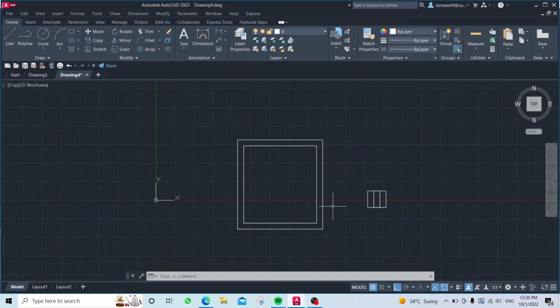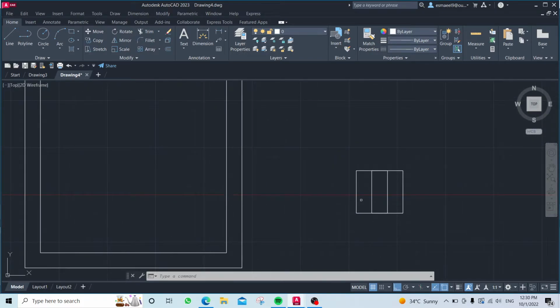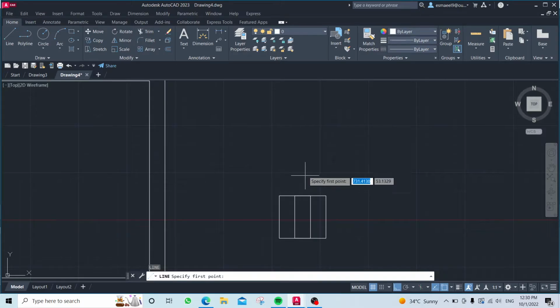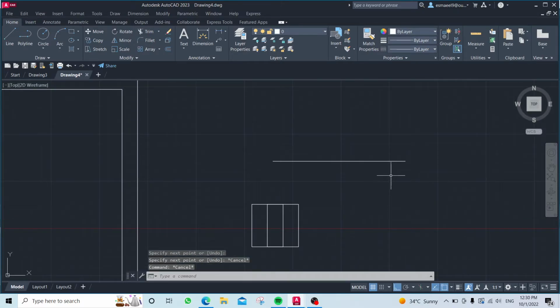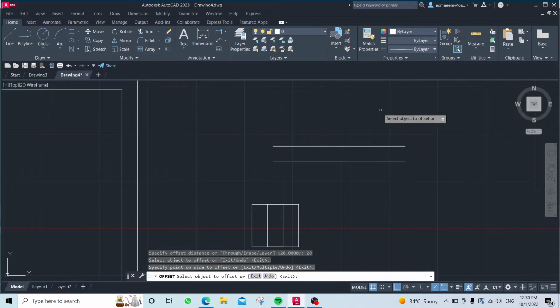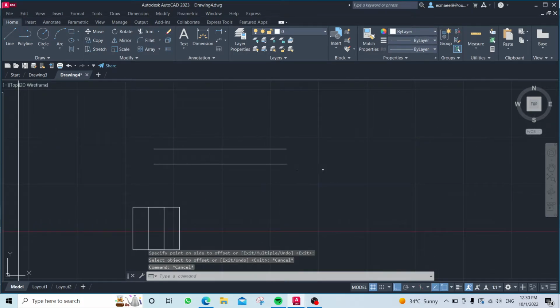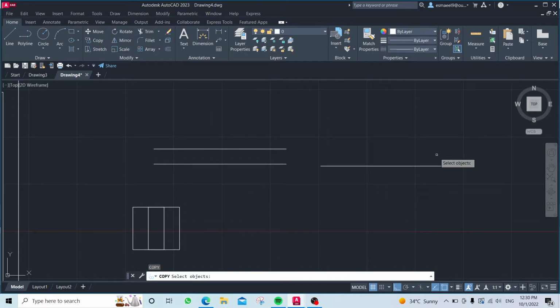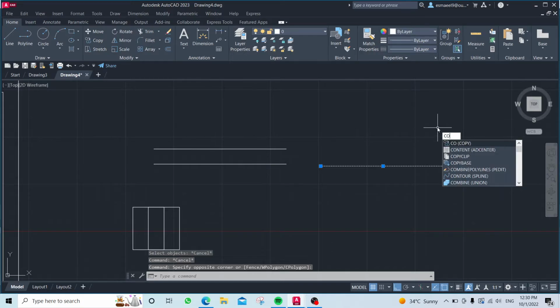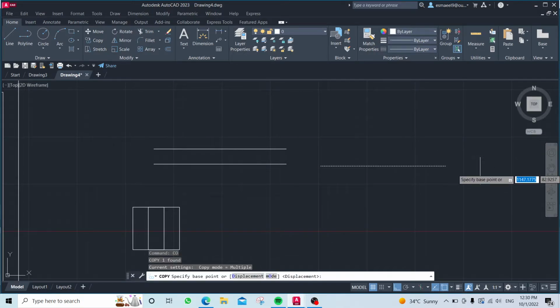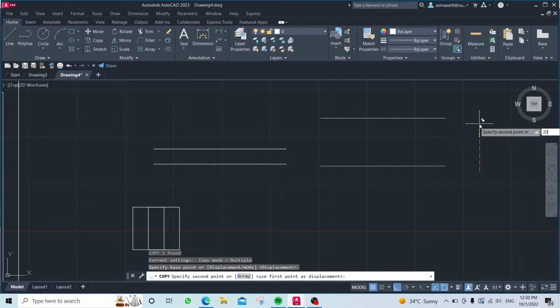They are similar to each other, but you can see the benefit of them, because if you just use a line, for example, like this, and then click offset, which is O, and then space, let's say 20, space, click in here, and then go up, and then draw the same line, and then use CO, or before, let's select our shape, CO, and then click space, and then click any point, go up, and then say 20.